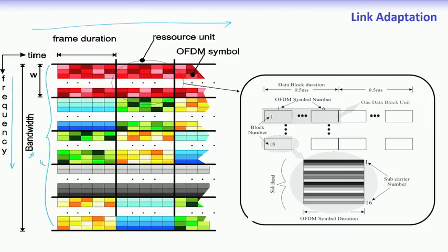So, this is your FFT operation or IFFT operation, and the number of subcarriers NSC is basically defined over this. Okay. So, that means one is having n number of subcarriers. So, when we said 2048 and we said 20 megahertz of bandwidth, this entire bandwidth is let us say 20 megahertz. It can be different values as described in the other picture, and FFT size would be whatever is the total number of subcarriers in this.